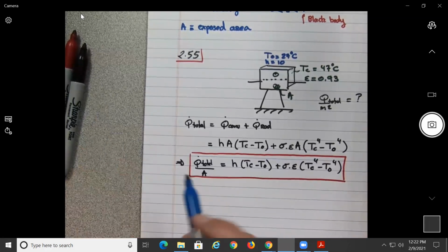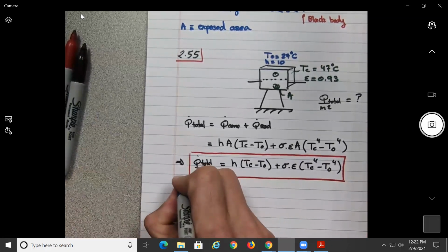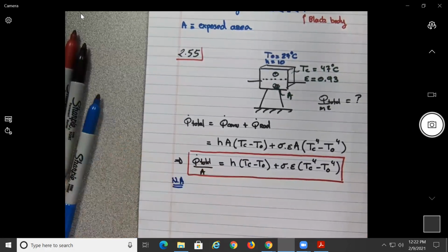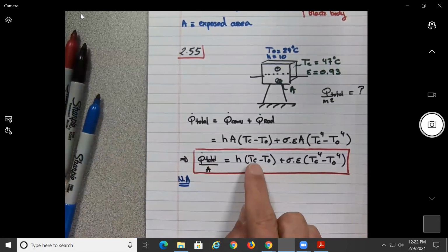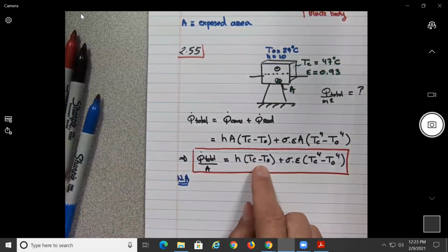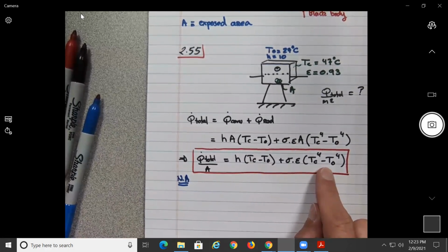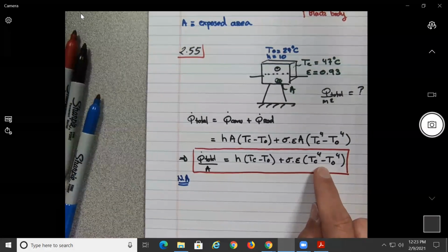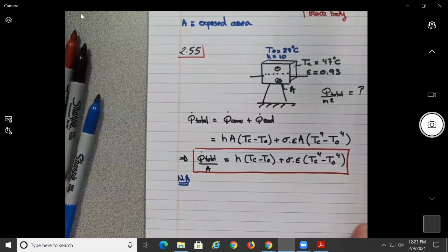Okay, so now for the numerical application, I want you to be careful, because in this case here, can you keep the temperature in Celsius? For this term, yes, because the difference of temperature in Celsius or not will be the same, no? But can you do the same thing here? No, so you need to have them here, yes or yes in Kelvin. So I would suggest to move everything to Kelvin and do every calculation with Kelvin, no?